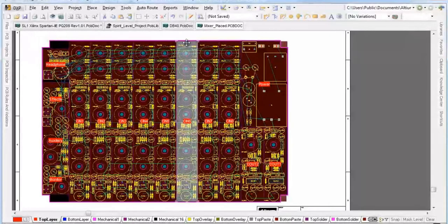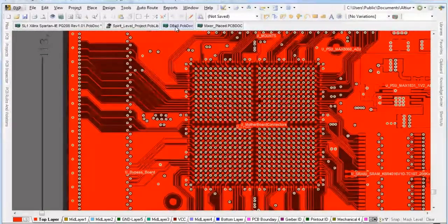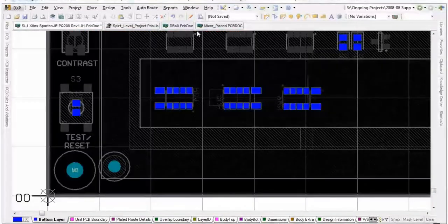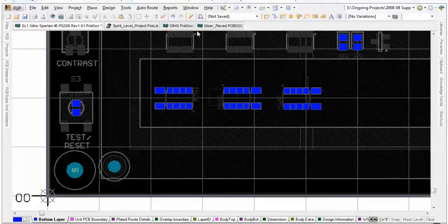In Altium Designer, rooms can be applied to different areas, be it for multi-channels, like in our mixer example, or rules related, say for track widths and vias in a BGA. Another handy feature of these rooms is to use the query function as a filter. So let's look at how a simple check on the orientation of your components can be carried out.